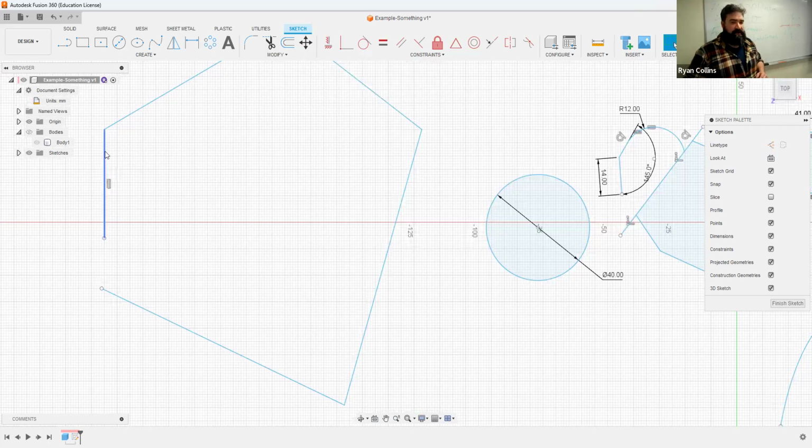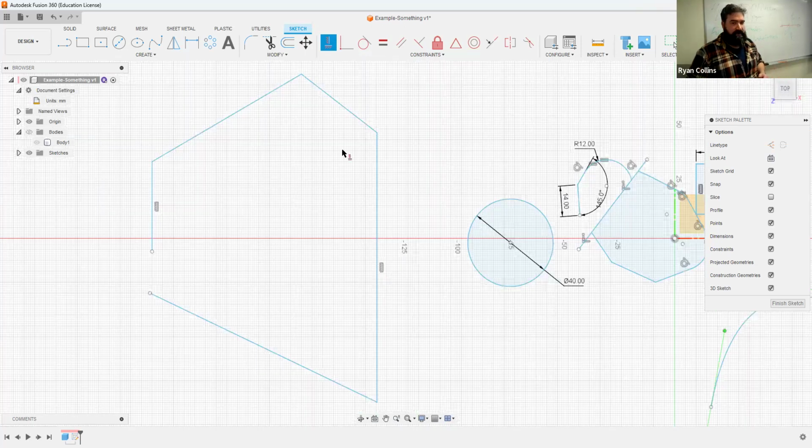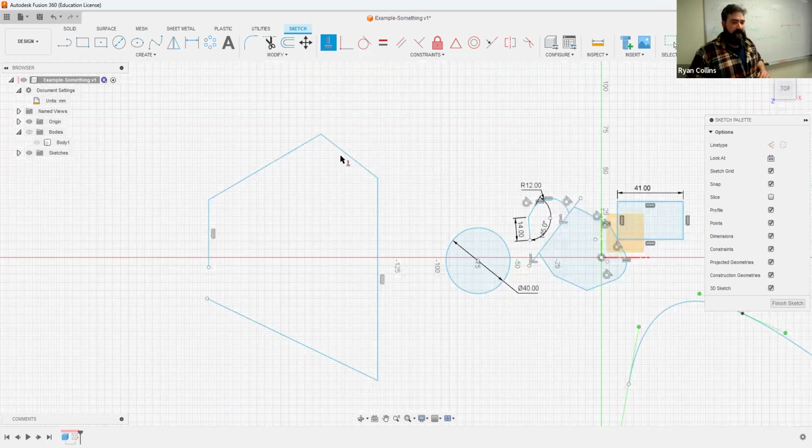So that one is horizontal vertical. It's already there. If I click that, it's going to give me an error. Okay, great. But I'm going to click that, not hit escape. But what if I wanted that line to also be vertical? Click it. I have the constraint active. It snaps that line to be vertical. It's going to snap it to the closest option, meaning it's not going to make this one vertical. It's going to make that one horizontal.